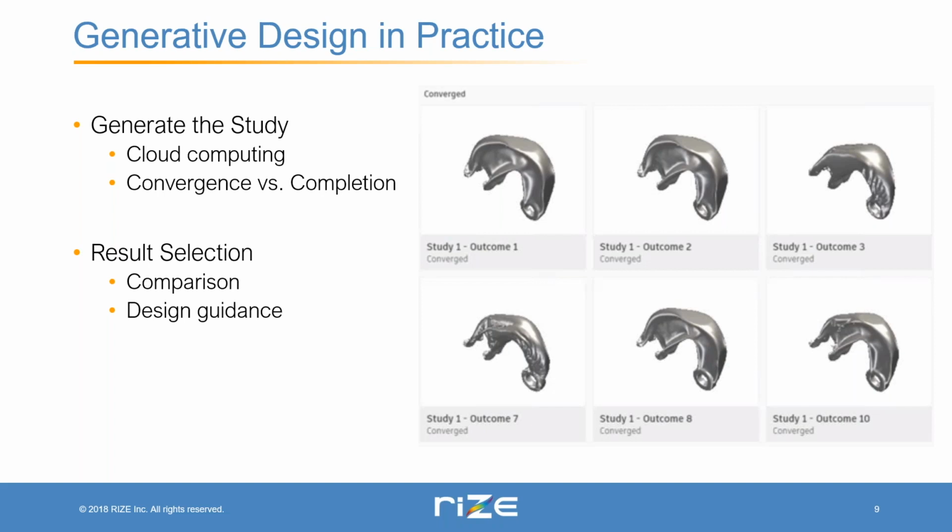There are a few different types of solutions that the software may arrive at. The one that you are looking for is a converged solution. This is when it arrives at an optimal solution, and it is putting that forward as something that you would want to use. The other option is a completed solution. These are often cases where the part could not arrive at a solution and sort of moved around and got unstable and didn't produce something usable.